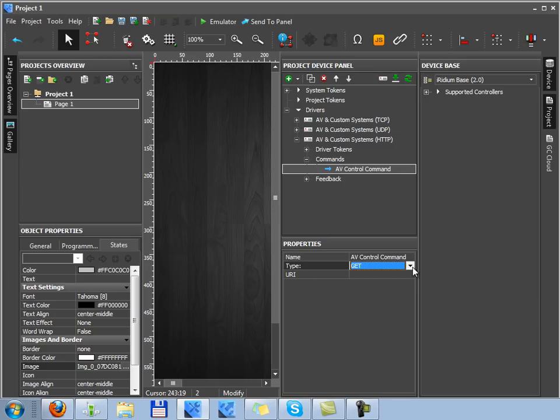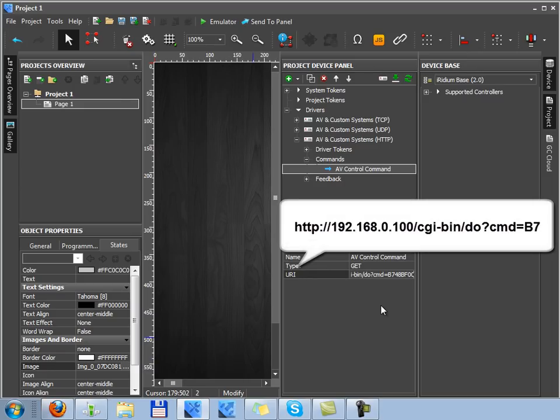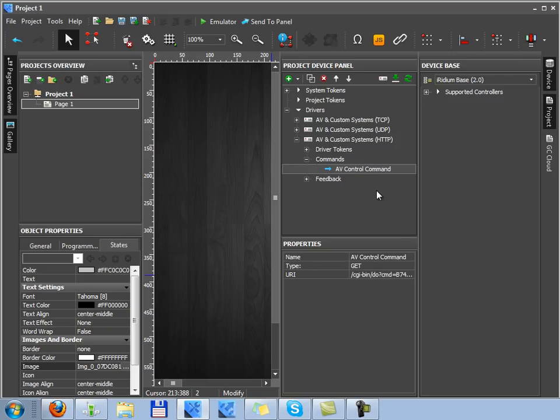Data of the GET format is sent by adding it to the URL address of an executed script. To create a GET request in the HTTP driver, you should input a command and delete part of the command, that is the main name of the control system. Meanwhile, the front slash of this command must be in its right place. You can create lots of commands.